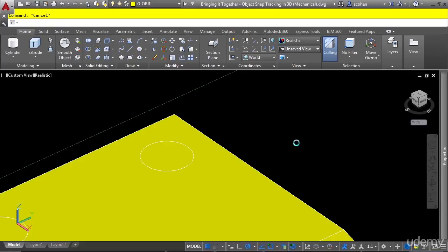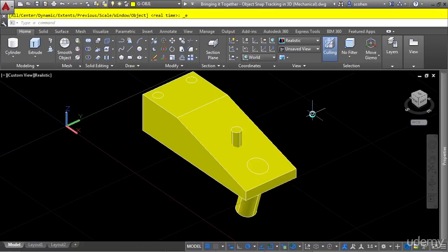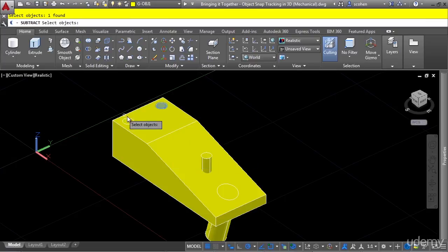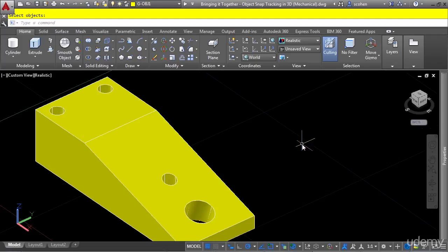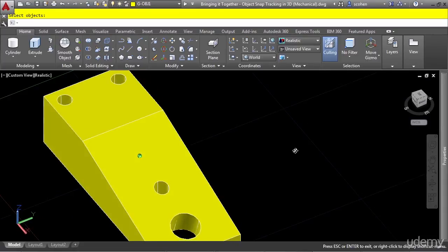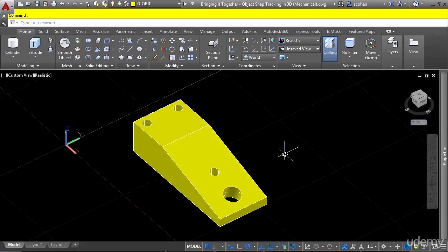We now have all the objects we need to create our holes. Although we have not discussed the Boolean operations, we will discuss them in future videos. For now, navigate to the Solid Editing panel and choose Subtract. First, pick your main solid and press Enter. Now choose your individual small solids that you want to subtract out. Press Enter, and as you can see, we have our holes completed at the correct projections and angles, changing the UCS and using 3D snaps.